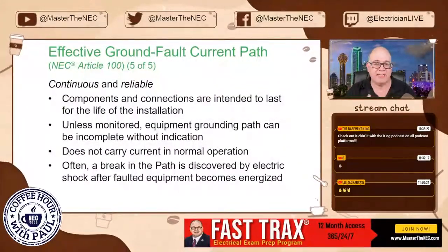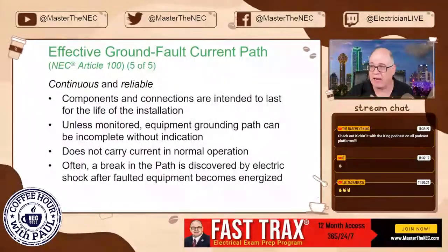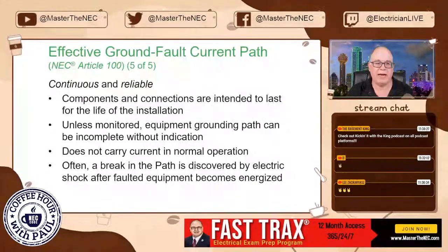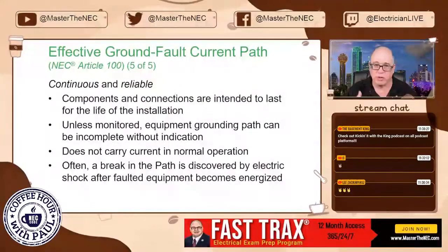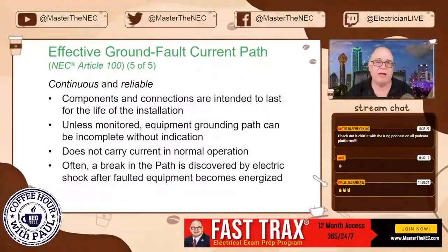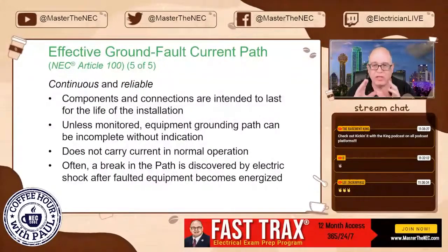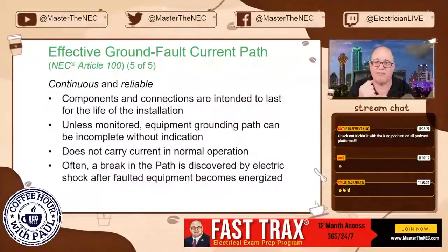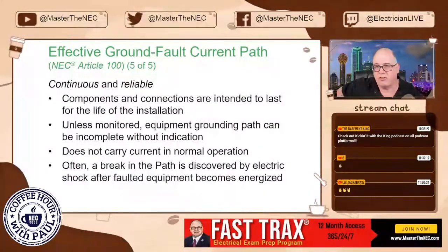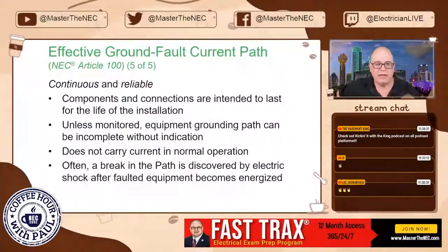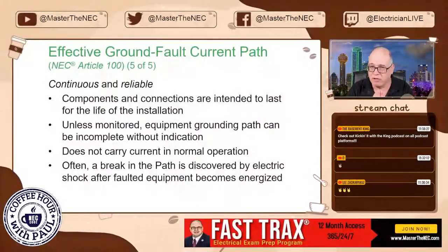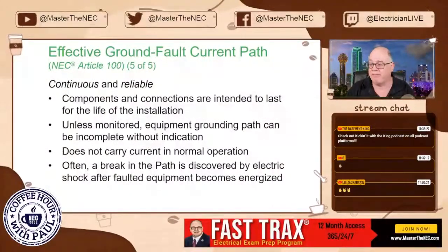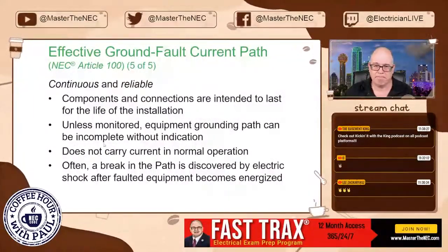It's not expected that you're going to come back and check them, even though in a lot of commercial applications, they do annual torquing and checking. The concept here is that when you do it, it's a one and done. So put that wiring system in so that you know it's done. Tighten everything, wrench tight, do what it says, make those terminations, torque it, do everything that you need to do to make sure that you're doing it right because it's for the life of the installation. Okay?